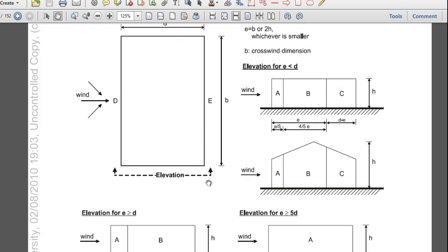Depending on the software you use, if the normal to the longitudinal direction of the building is your 0 degrees, then this automatically becomes your x-axis. So this is your x, and that's your y, and z is upwards, perpendicular to this plane. Then you will have to apply the wind loads in those orthogonal universal coordinate system directions.